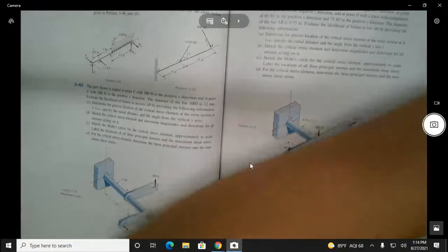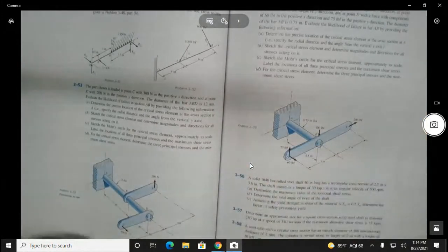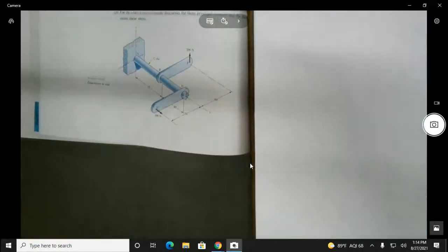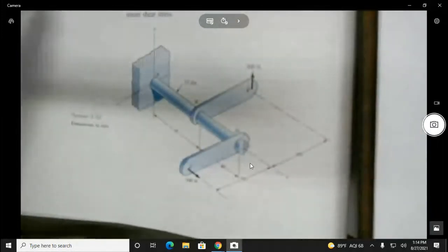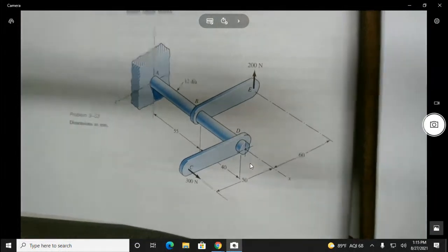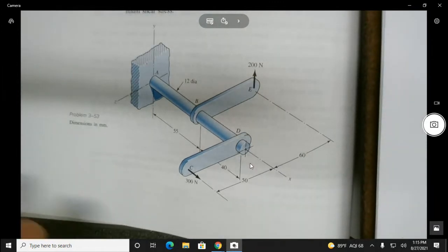Sure. All right, so the first aspect that makes these difficult problems is finding the reactions, doing the statics. So let's go for this guy right here. And even before that is just trying to picture what this looks like in 3 different views. So let's try to do the good place to start. We like X and Y, right? X and Y is a good place to start. So we want to try to sketch this thing in the XY plane.